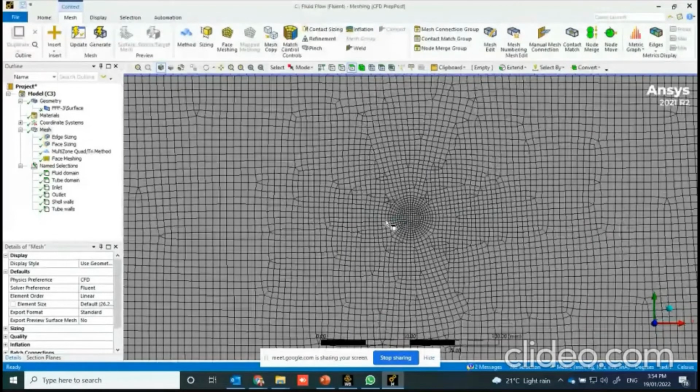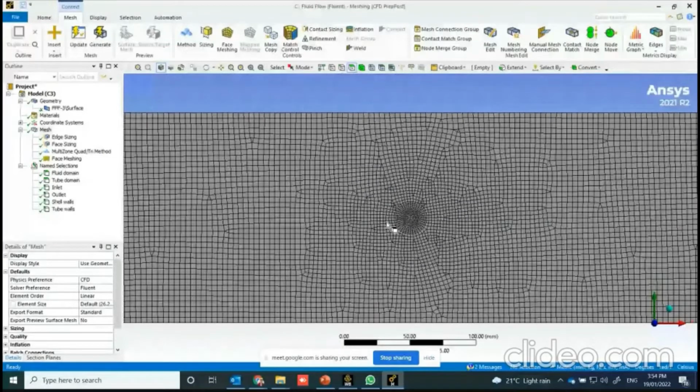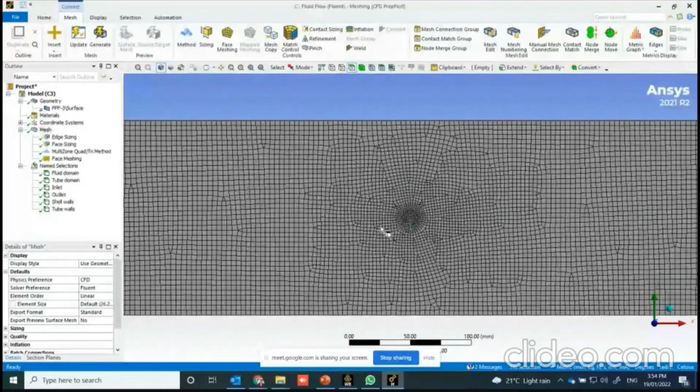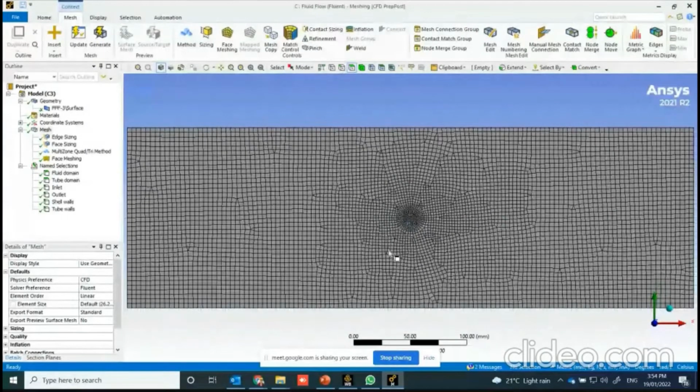You should know something about the Y+. Hopefully, most of you know about the Y+. Y+ is a concept that is mentioned and emphasized in turbulent flow. And again, it is for capturing the effect of the flow structure and heat transfer, for example, near the target wall or any surfaces.